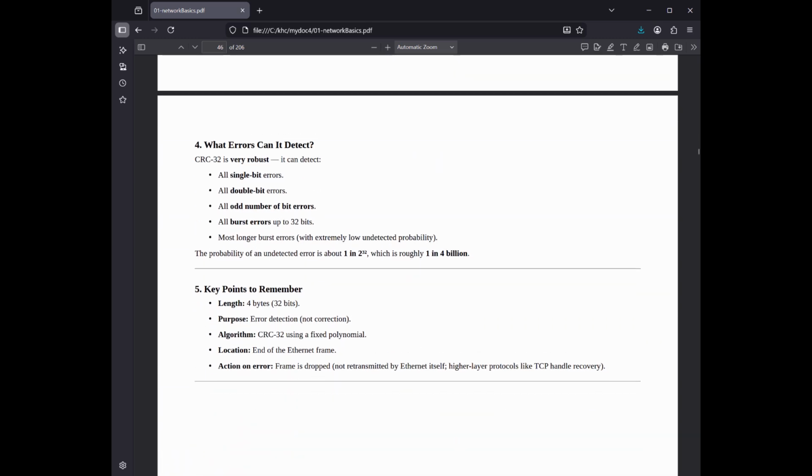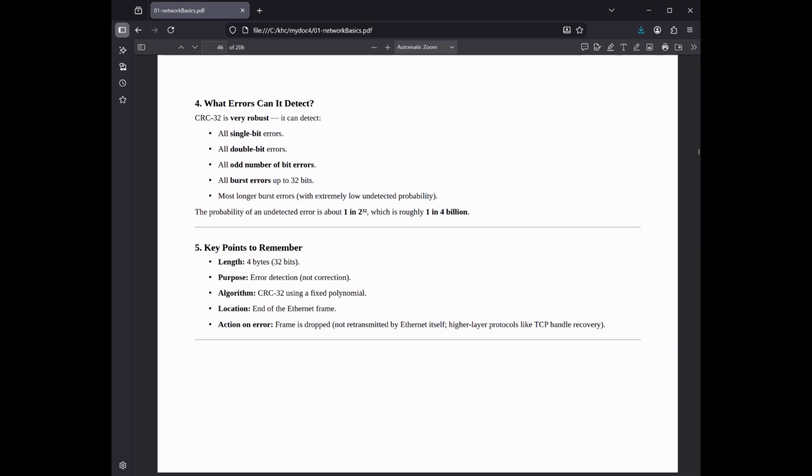The IEEE 802.3 CRC32 polynomial, the standard generator polynomial G(x) for Ethernet, also used in numerous other applications like PKZip and PNG files, is shown under representation and implementation details, polynomial form. In the equation above, each x^n term corresponds to a bit position in the binary representation, where the coefficient is 1.